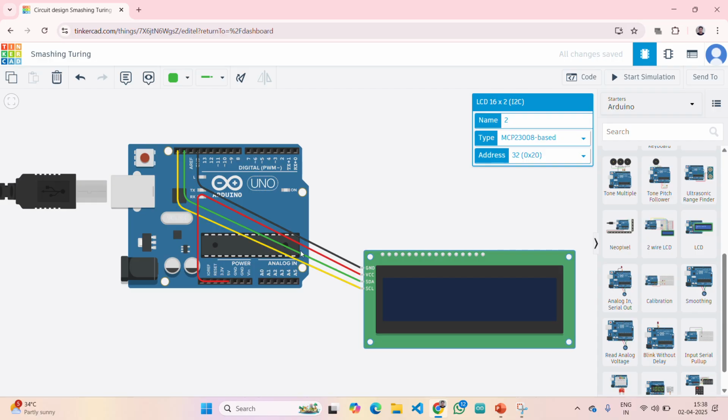For this, you need not declare pins as per our usual way. There is a separate package for it. Nothing but one additional library we are going to use for this LCD. I am also going to explain about it. As per that, this SDA should be given after this AREF pin and SCL the last pin. This facility is only available in Arduino UNO R3, because in the older Arduino UNOs there are no extra pins. It will be up to digital 13 and ground only. So you need to notice this while buying Arduino UNO.